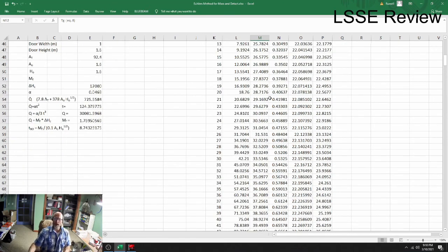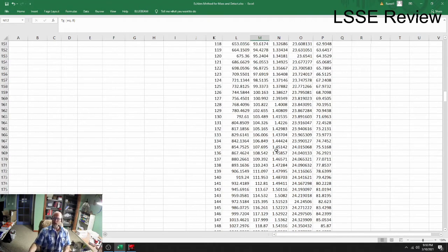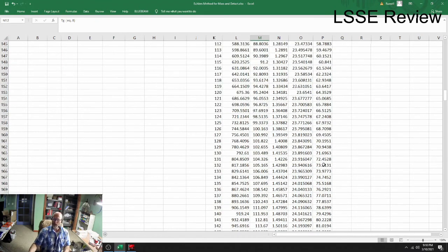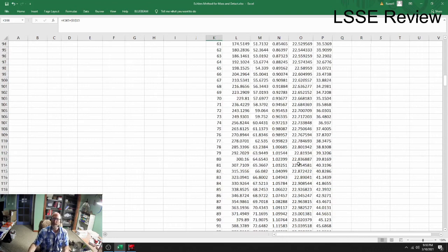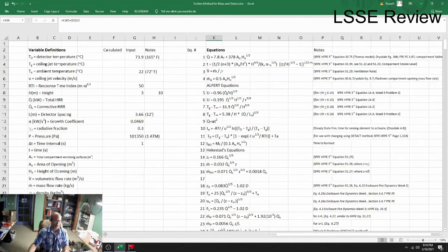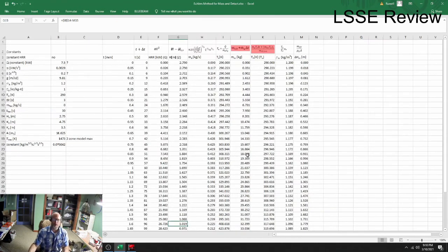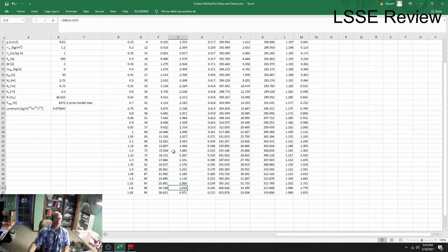Point is, you're not technically in this configuration even going to trigger until you are at about 133 seconds. But remember, your Q value in this particular scenario for flashover happens at 124 seconds. So that's what you need to keep in mind. Anyway, I could go on and on. There's a lot of different values to play with. I want to show you this. This is a little spreadsheet put together to help understand heights.